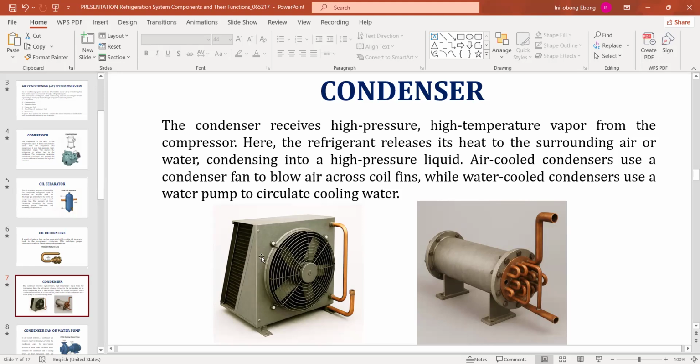In some systems, the condenser uses a fan to expel the heat, while in some systems, like industrial or vessel ones, they use a chiller or cooler, so the seawater cools it and then goes out. The diagram that I was asking you about, what is missing there, was the condenser fan and the evaporator blower in that diagram.